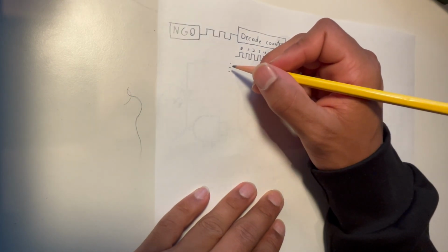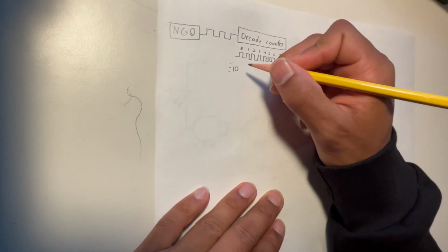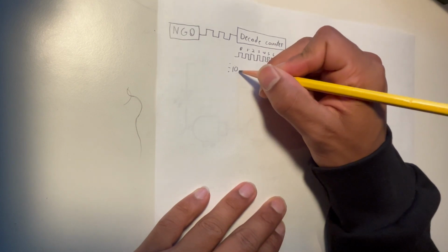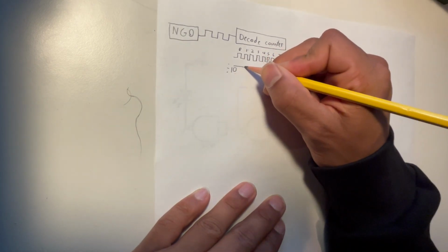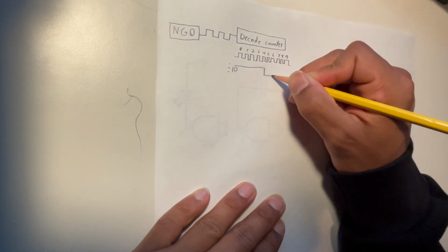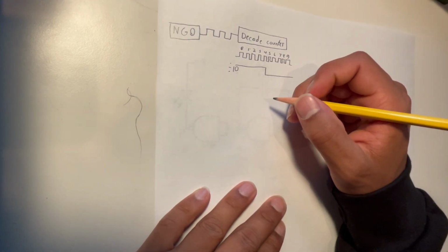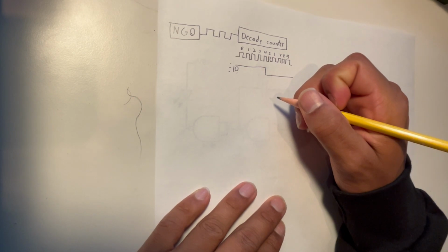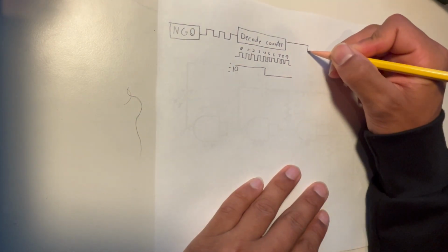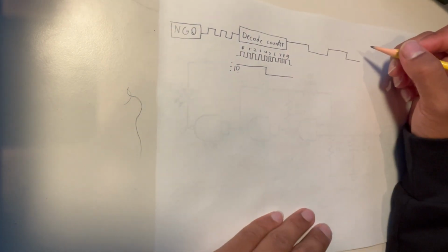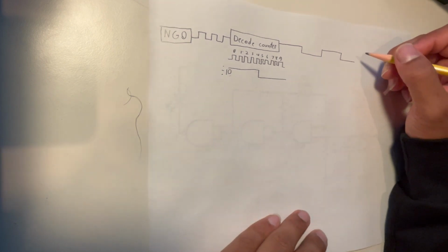The decade counter serves one additional purpose. The divide 10 pin is high for the counts 0 to 4 and low for counts 5 to 9. This effectively causes the pin to divide the clock signal frequency by 10. This function is useful in the case of the counting circuit to reduce the rate of counting enough to properly observe the changes. The divide 10 output of the decade counter is connected to the clock input of the BCD counter.